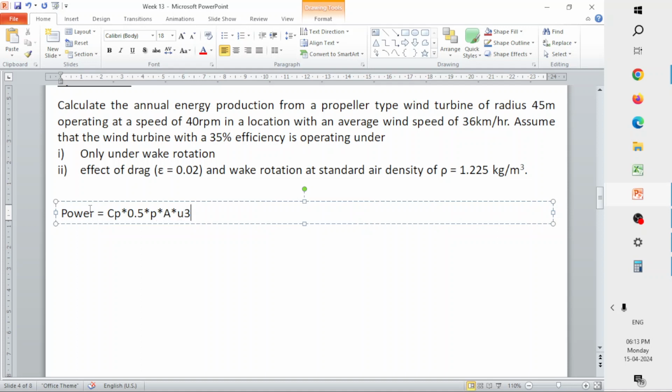I hope you remember how we solved this. It is the kinetic energy of the air molecules that is getting converted to the wind energy or wind power. So we take wind power as nothing but the differential of kinetic energy with respect to time. From there we derive the steps, and at the end we got the formula for the power that is available in the wind as half rho A U cube. So you can always check that derivation. It will be there in the week 11 live interaction session, also in the video lecture.